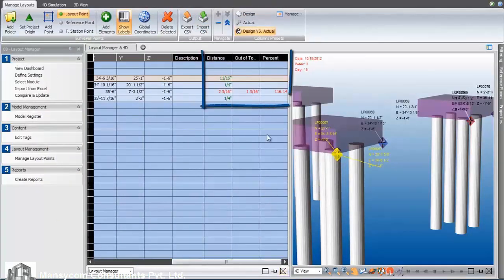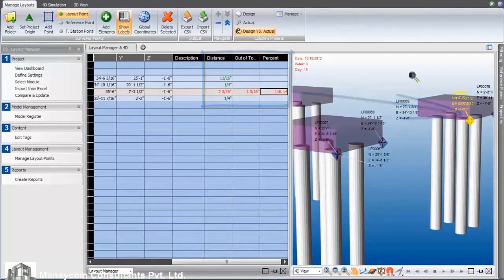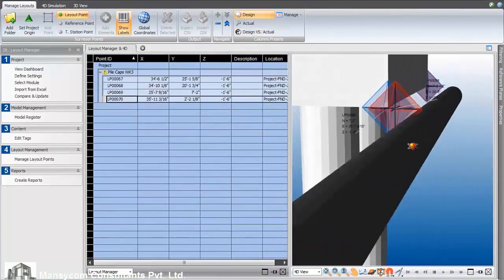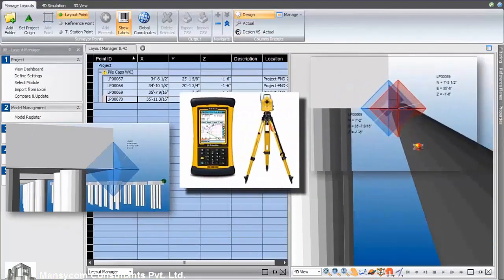After the import, any out of tolerance points will be flagged so that they can be investigated by the team. If this problem was noticed only after installing the pipe next to the incorrectly located pile caps, it could impact the location of slab penetrations, fixture positions, and even architectural wall layouts. This validation process, if implemented correctly, will provide an early warning system with the potential to save huge amounts of field rework, RFIs, and late reactive design changes.